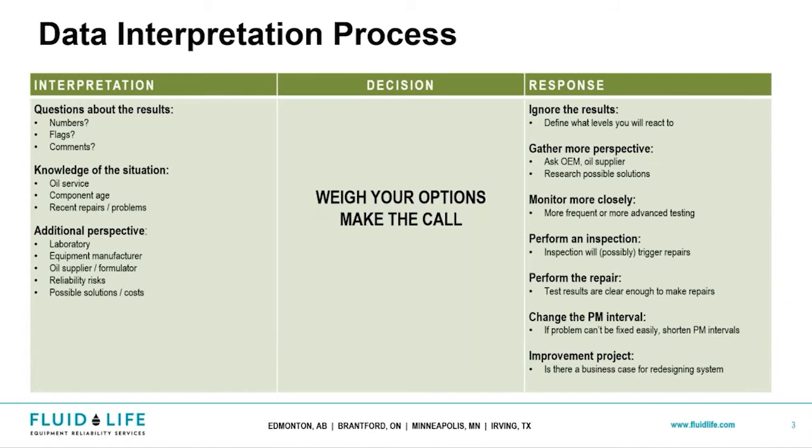So where do we start? When you start an oil analysis program, a lubrication analysis program, a grease analysis program, you have to take into account the data interpretation process. That starts in kind of a 3-step setting where you have interpretation. That's where you, first of all, take the sample, make sure that it's a consistent format, you know why you're taking sampling, you know who's taking the sampling, you know in what manner they're taking the sampling consistently, and then you go ahead and you get your results.